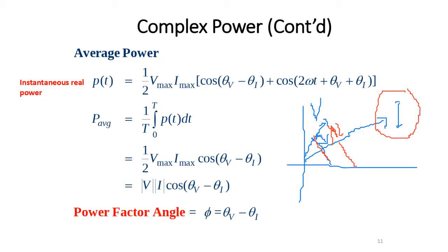We don't want the power factor to be leading, and we don't want it to be lagging too much. So 0.87 will be okay, 0.9 is good. If you go below, then you need more power to push, as we will discuss later.